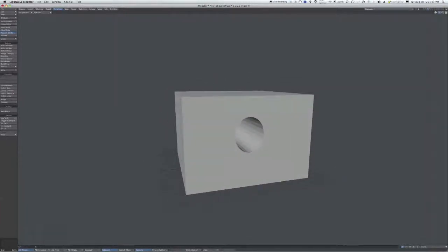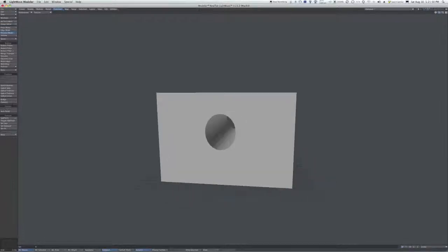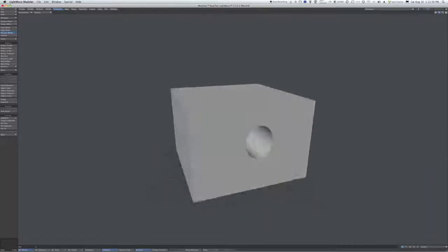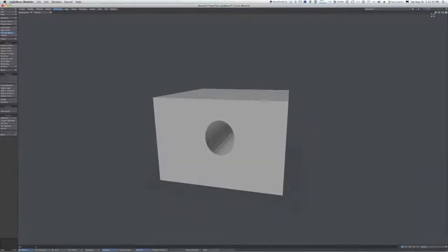But the bigger influence is the fact that the plastic shrinks a little bit. Now, most printers can print the outside the right size, but by the time you get to the inside, everything starts shrinking and pulling towards that outside layer, and the holes are smaller. How much smaller? Well, that's the million-dollar question. It can be anywhere from 0.5 millimeter smaller up to 2 millimeters smaller. Well, that's why we have little guides that you can print.